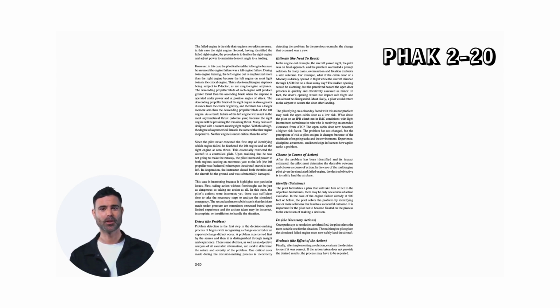Estimate the need to react. In the engine-out example, the aircraft yawed right. The pilot was on final approach, and the problem warranted a prompt solution. In many cases, overreaction and fixation excludes a safe outcome. For example, what if the cabin door of a Mooney suddenly opened in flight while the aircraft climbed through 1,500 feet on a clear, sunny day?